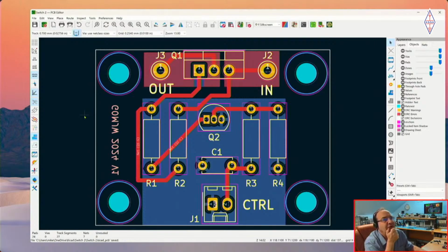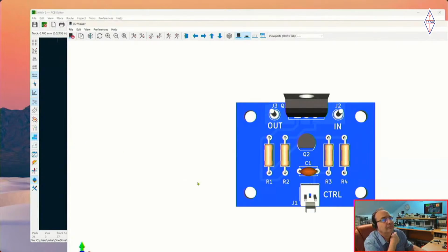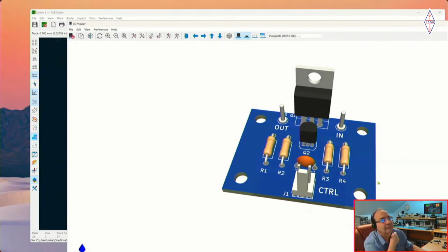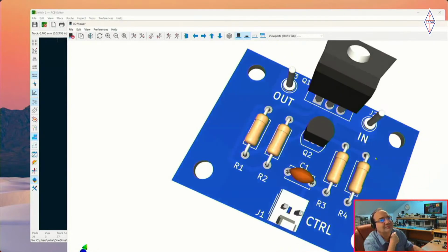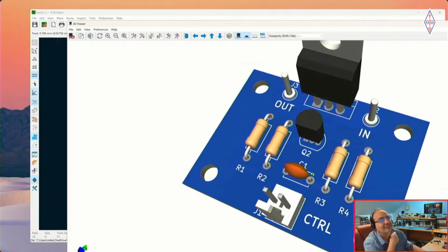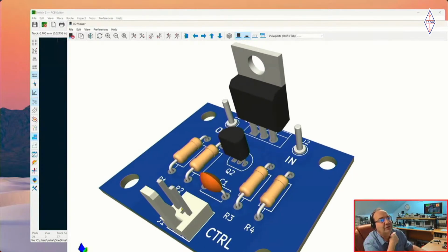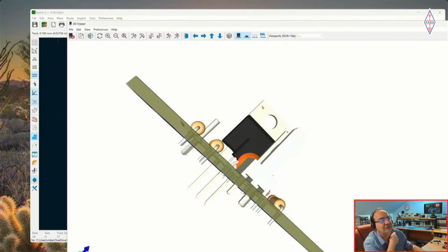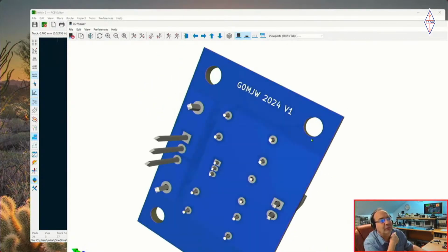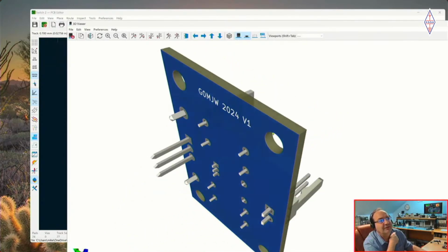One of the party tricks, I guess, of KiCAD is the 3D viewer. I'll just show you that. Oh, that makes all those details about getting the dimensions of the component at the beginning really worth it, doesn't it? And that's all built into the standard KiCAD program? It is, yeah. So you can look at that board now and you can see the clearance between various places. For particular projects, that's actually really important, especially if you want to see if one thing is fouling another. So there's the back as well with the silk screen on it.